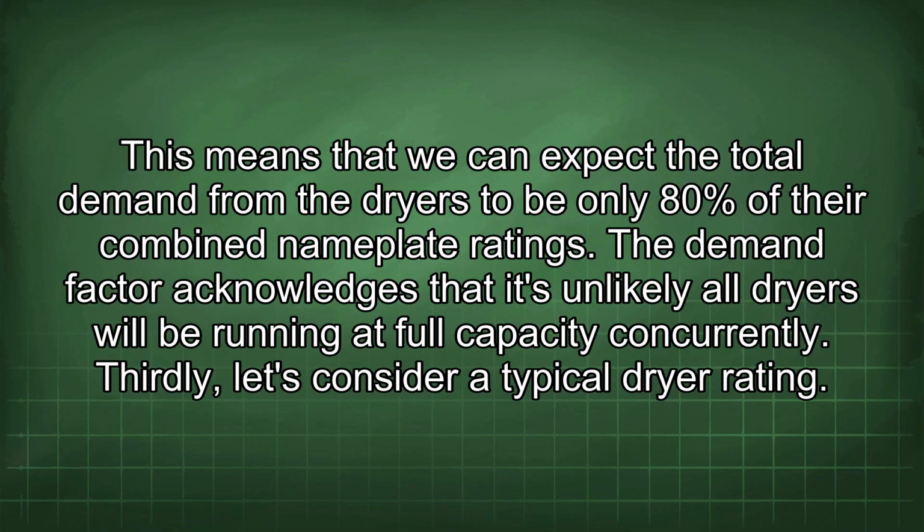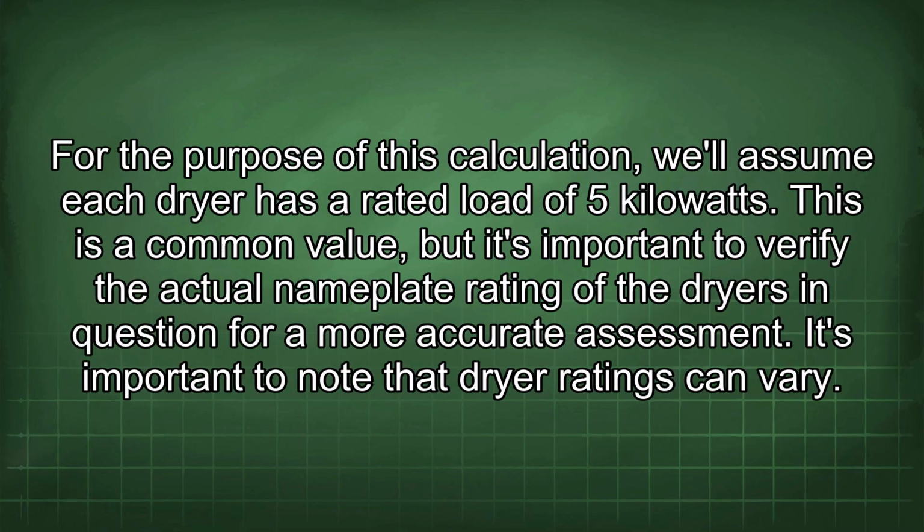Thirdly, let's consider a typical dryer rating. For the purpose of this calculation, we'll assume each dryer has a rated load of 5 kilowatts. This is a common value, but it's important to verify the actual nameplate rating of the dryers in question for a more accurate assessment. It's important to note that dryer ratings can vary.